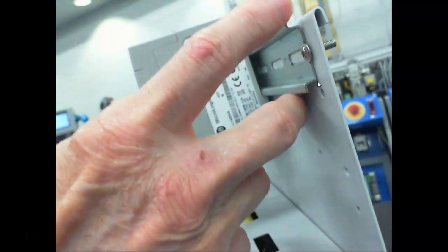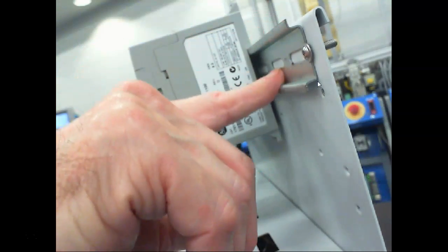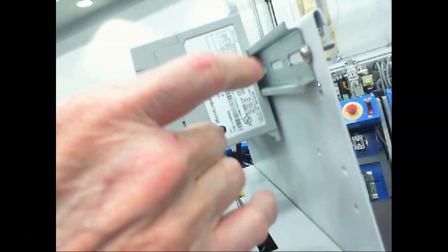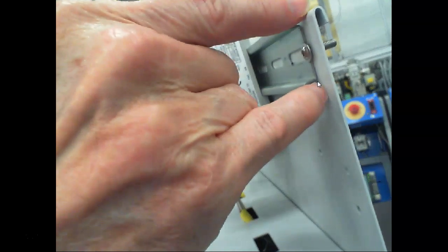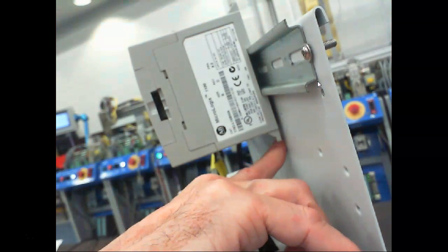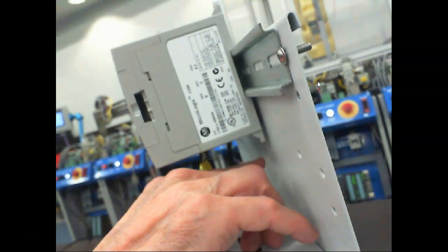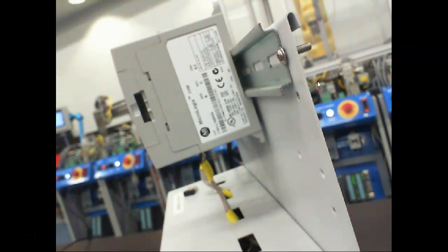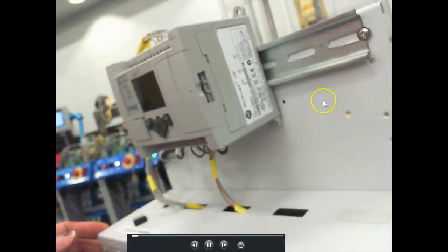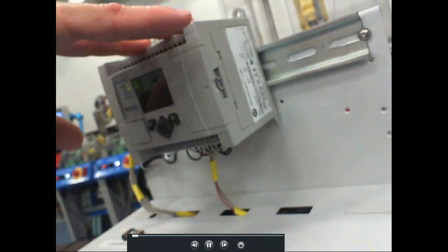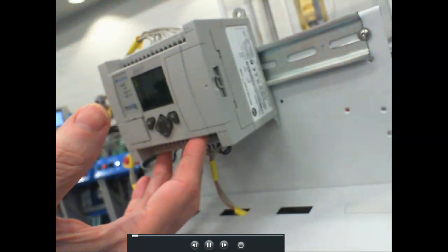And these usually mount on what we call a DIN rail, and these are standard sizes. This is called a top hat DIN rail. You can see because if you flip it upside down, it kind of looks like a top hat, and it's got these grooves, and then the PLC latches into it. To take the PLC off, you just undo some snaps and snap it off. What's nice about this unit is we can mount any PLC on it that mounts this way. This guy here has a number of internal inputs built into it, and a number of internal outputs built into it.